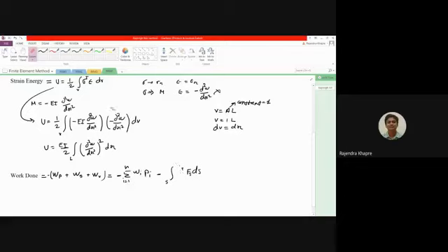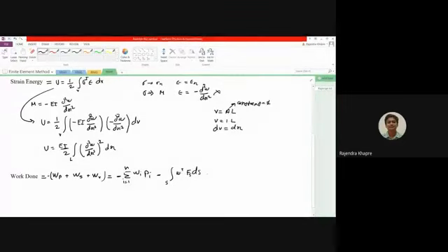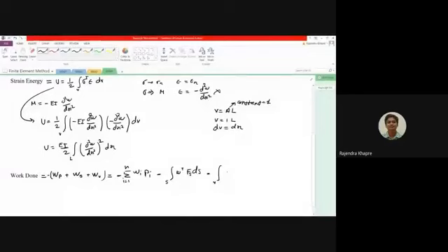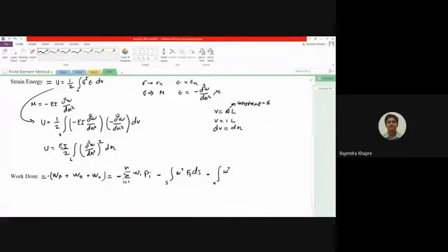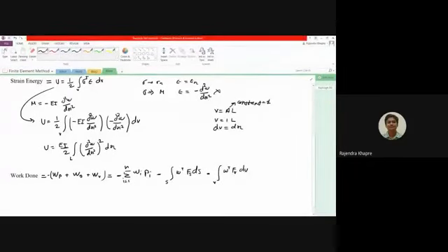We are interested in the displacement perpendicular to the x-axis, so this will be replaced with W. Minus the volume load will be exactly the same as the previous one. Only thing is, in place of U, you now have W transpose, FV over dV. So these are some changes which we have to make when solving beam problems.